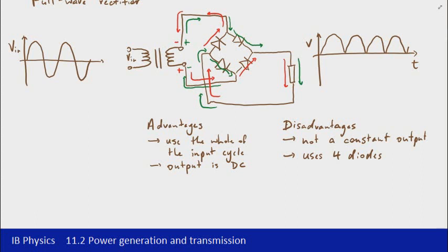So let's say we use that idea of using a capacitor again. In this case, because the cycle is much faster, so it's coming back up again in those negative half cycles, you can see there that the ripple is going to be much smaller as a result. So that finishes off the rectification. We'll finish up this subtopic just by looking at a few other bridge type circuits, not so much related to AC as such, but using this idea of this bridge of 4 components in order to figure out other quantities.